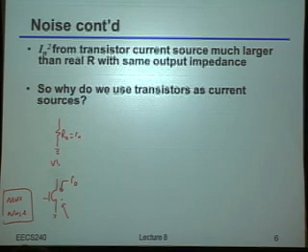Okay, but the sensitivity is more. So you said the sensitivity of this is more. Current will change. Well, maybe. Yeah, no, maybe not, right? Because like I said, I've made this resistance the same as the output resistance of the transistor, right? So at least at a particular bias point, the sensitivity is the same. But what are you paying for it?